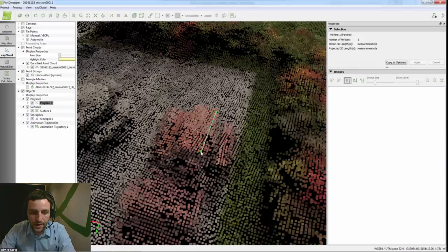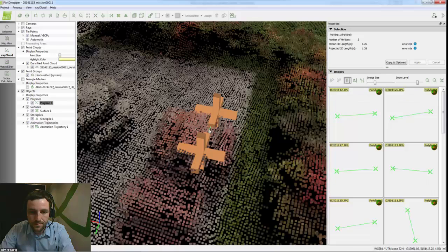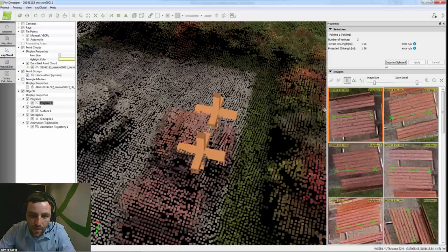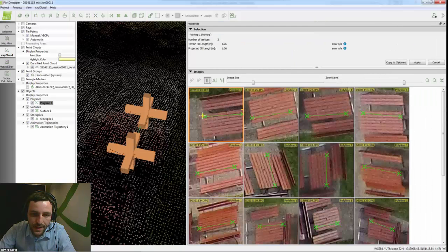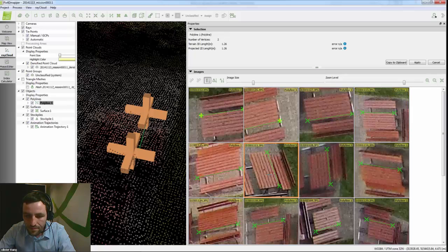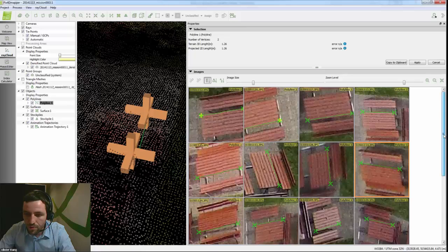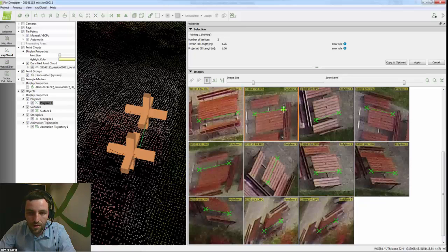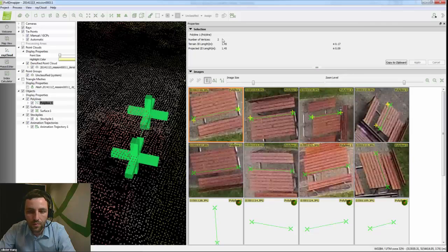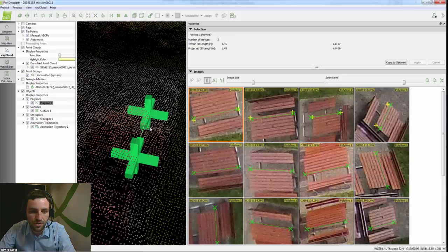So you start by doing an initial guess, and then you can use the images to refine your initial guess into a very, very precise measurement by clicking, by helping the software to go exactly on the border of the bench. You see live the reprojection of the measurement you just did over all the images, which allows you to get a confirmation on how accurate the measurement you just did was. By applying, you now get the real estimates of the lengths that you just measured.